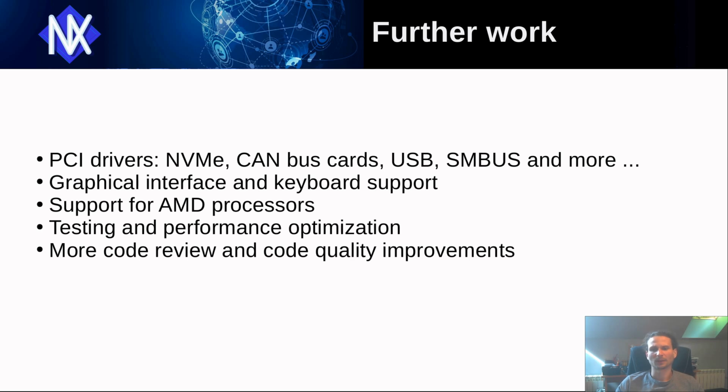A few words about what can be done in the future. First, we can add support for more PCI devices, including NVMe, CAN bus cards, USB and more. We can add support for graphical interface and keyboard support, so we can run NuttX directly on the hardware without need of legacy serial port or PCI serial card. Another thing is support for AMD processors, and of course we need more testing, performance optimization, more code review, and code quality improvements.